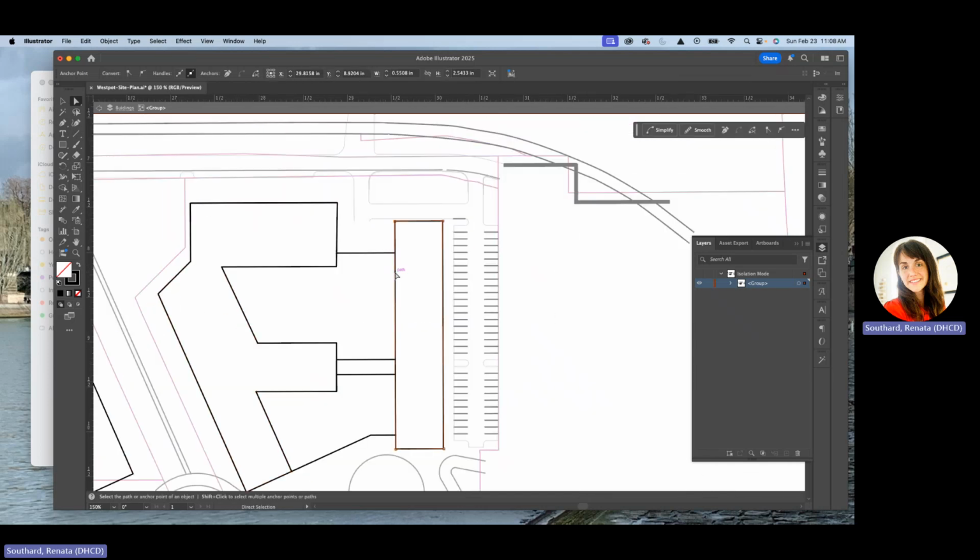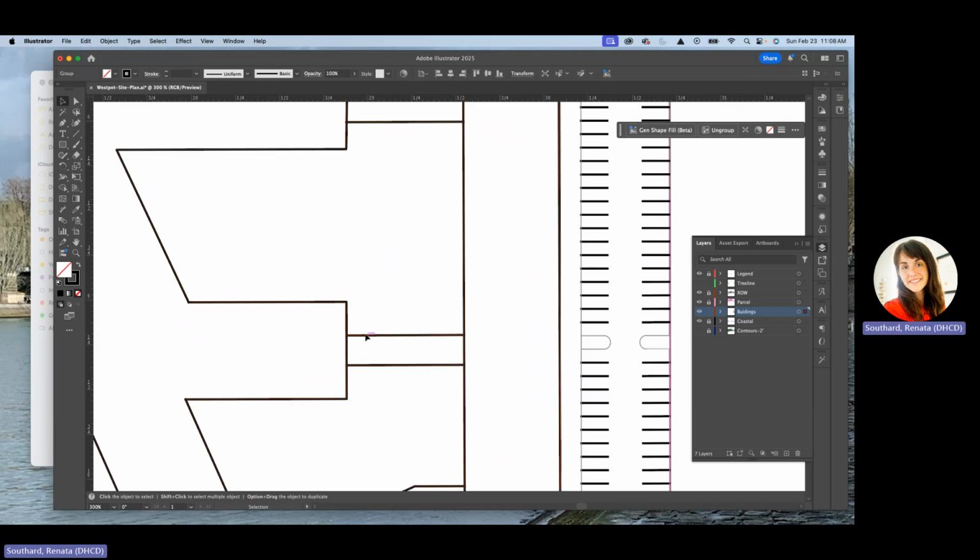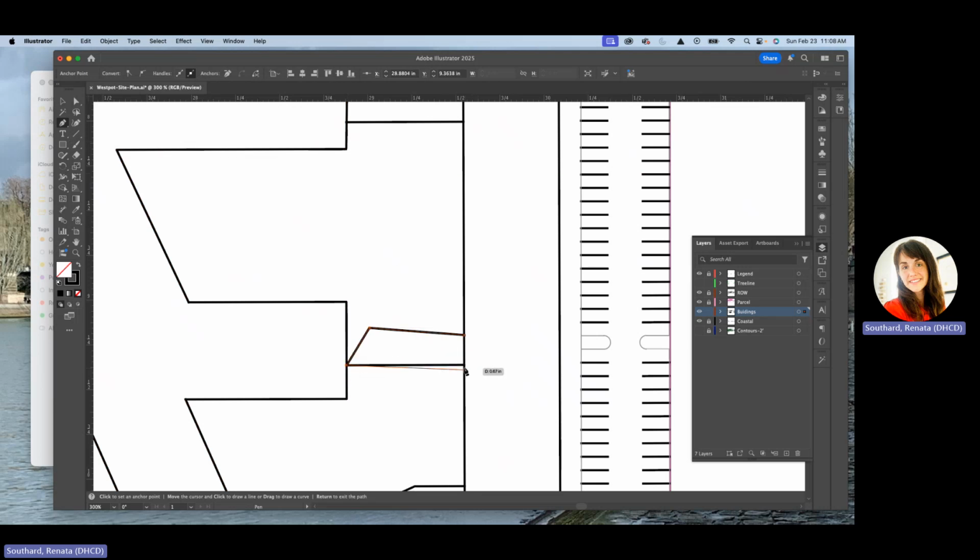And then this guy, that looks like it's a shape. This one doesn't look like it's a shape. Maybe I want to put a rectangle there. I could either, with my selection tool, delete those guys, or actually, oops, I'm going to undo that. I don't want to do that. I'm going to use my direct selection tool here. I'm going to use the point tool. So this one here, and I'm going to add a point to it, and then I'm going to connect it there and connect it there. And then I'm going to move this back. So go back to my direct selection tool. That's this one. And move this back.